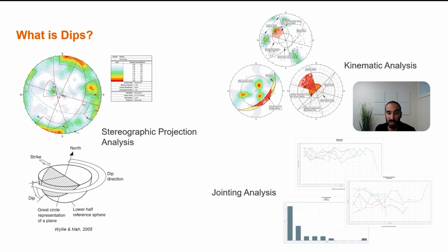Once the stereographic projections are completed, you can then identify critical zones, vectors, and intersections on a StereoNet overlay with the kinematic analysis of planar and wedge sliding or direct and flexural toppling failure modes. You will then also have the option to export kinematic analysis results to a spreadsheet program containing critical vectors, intersections for all failure modes.